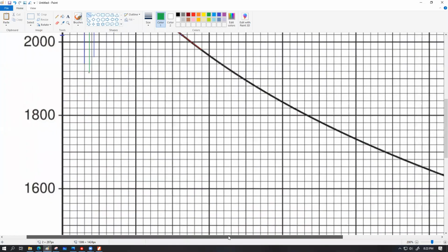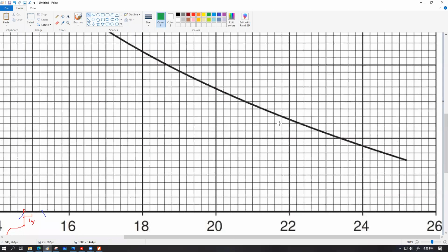But if you use that same information for the later part of the graph, let's say you're trying to find out the uncertainty for a temperature value of this much, over here. So have a look. In this case, the temperature would be given by this line, and a 20 ohm positive variation should give you this line, which is gonna give you a cross-off somewhere over here. So you see that uncertainty is really large. That's what I meant. And then if you go for the lower boundary, it gives you a pretty close cross point somewhere over here. So in this case, this much is your uncertainty. Because the graph is losing gradient, the same amount of vertical spacing is causing a bigger amount of relevant horizontal spacing.